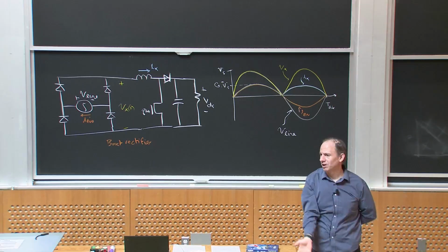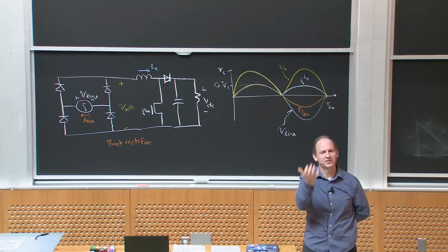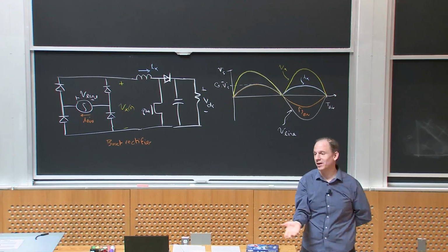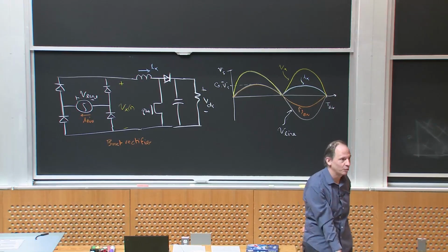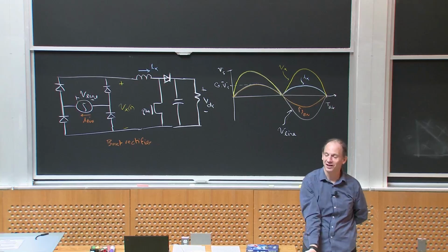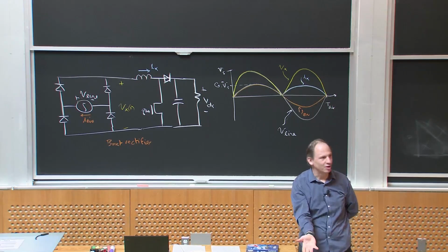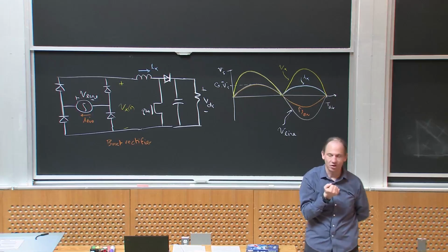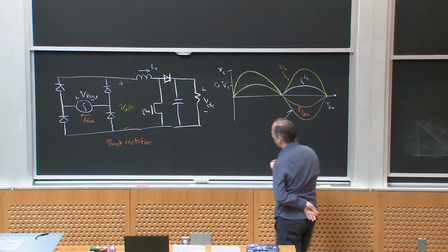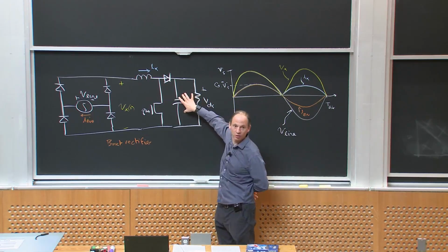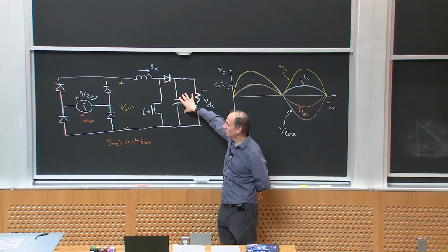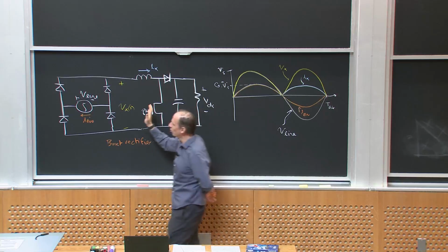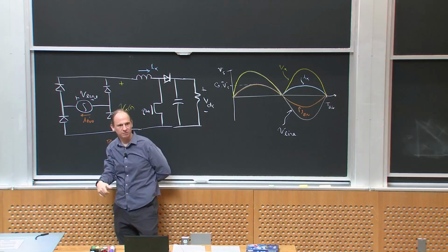But it can be plus 10%, minus 15% around that in practice, or sometimes even worse. But then I also have to make it run in some places in Japan where the line voltage might go down to like 90 VAC RMS, and I got to make it run in Europe where it can get much higher. So most of the time what people will do is they'll make this like 400 volts-ish for a single phase line, which means it can take sort of anywhere in the world's single phase AC voltage.